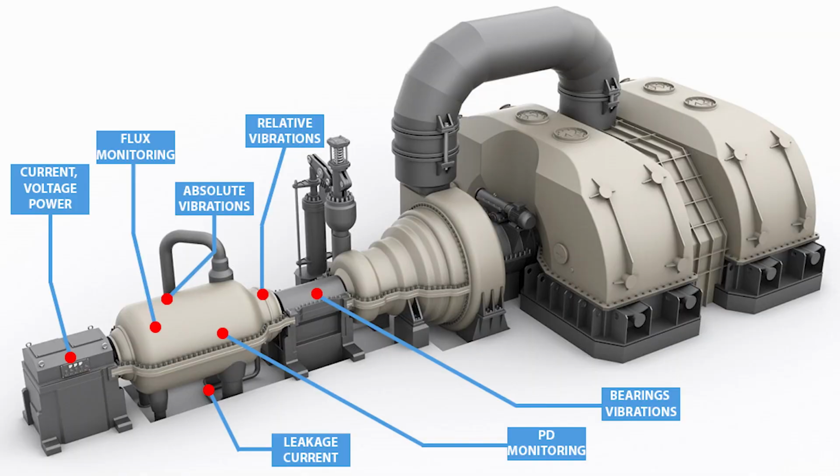For hydro and turbo generators monitoring, we provide monitoring of electrical, magnetic and mechanical parameters such as absolute vibrations with FFT analysis, relative vibrations, leakage current for insulation problems assessment, stator temperature, partial discharges and rotor flux.